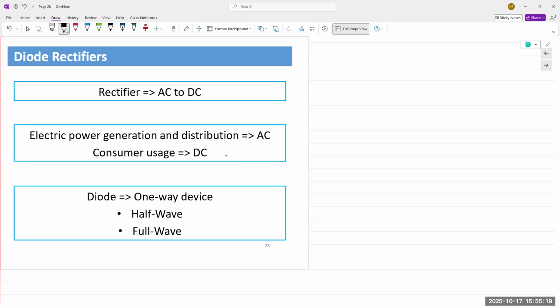When they were first coming up with the names, they said, okay, AC to DC is a rectification. We are rectifying it back to DC. And so they named these circuits rectifiers. And for DC to AC conversion, they said we are inverting the process, so we'll call them inverters. Inverters are now very common because California has a law: every new home construction must have solar panels on top, and all solar panels generate electricity in DC. If you want to feed it back into the grid, or use it as part of your home, then you need a way to convert that DC into AC. And so you have inverters mounted on the side of every home.